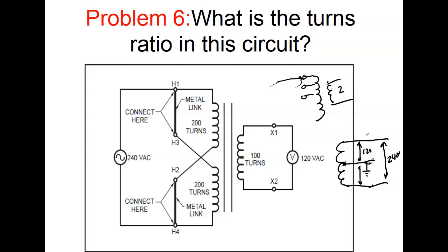So that's why you'll see two wires that are insulated. Those are the two outsides of the transformer. The ground is going to be a metal wire. That's your neutral coming down. So 240 basically is not referenced to ground. And then we'll take the chassis on the outside and ground it. If the 240 is running something like a water heater, we'll run a ground to the metal on the chassis.